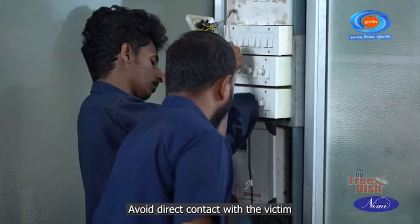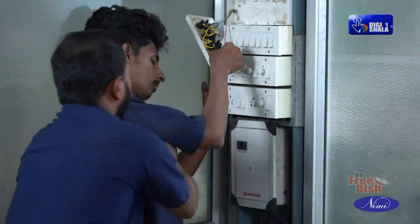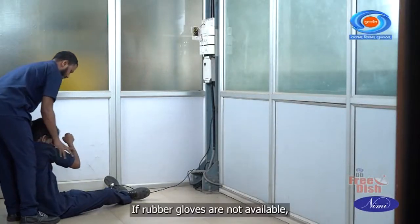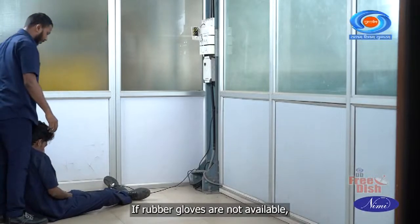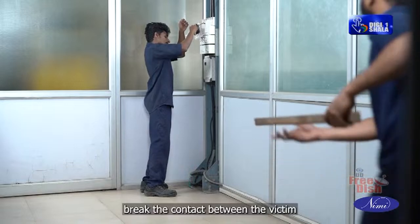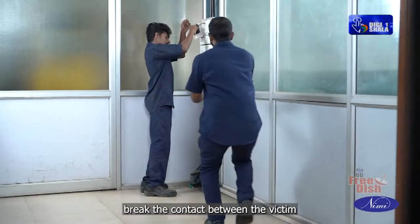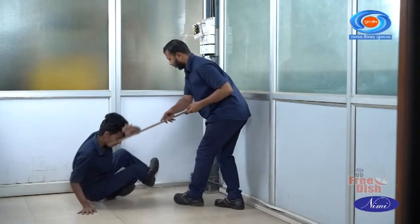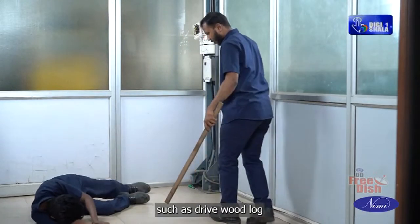Avoid direct contact with the victim. Wrap your hands using dry cloth or paper if rubber gloves are not available. Instead, break the contact between the victim and the electrical source by using an insulated tool such as dry wood log.